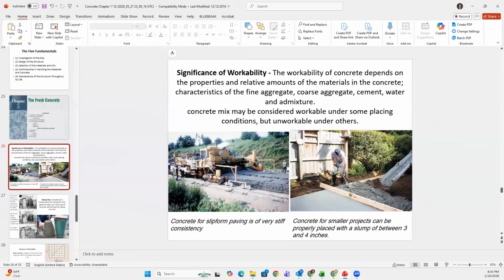because it is pneumatic concrete, pushed by air. So those kinds of concrete, even though I'm not talking about strength, I'm talking about workability. They all have to be high strength. But how you achieve high strength and different workability is a job for the right mix and batch plant, knowing what you're doing.